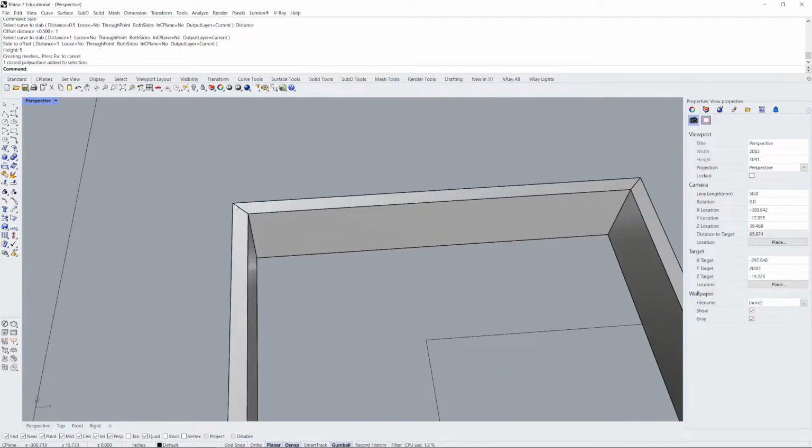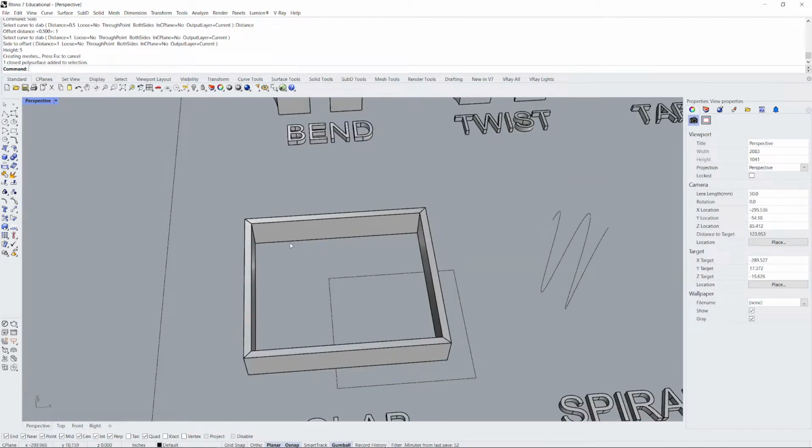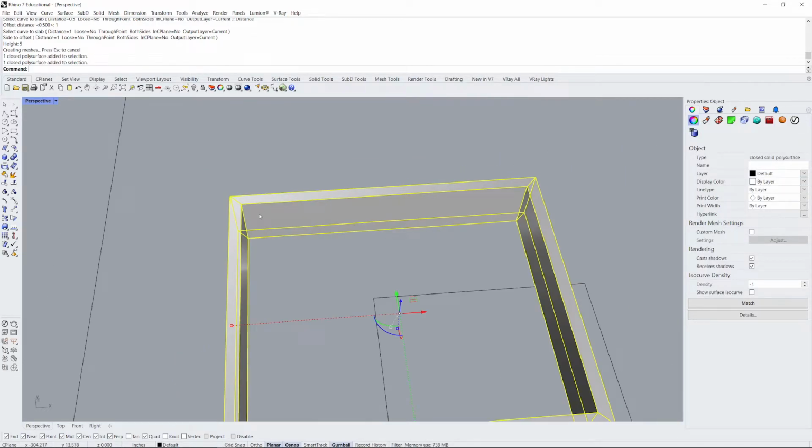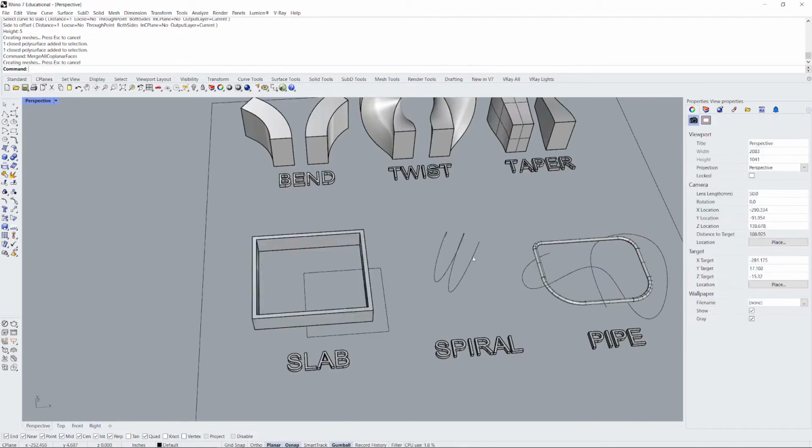It does kind of do a weird thing with how it creates its corners. If you extruded that after offsetting it, you wouldn't have this seam here. We could try typing in merge all coplanar faces. So there you go, that worked.